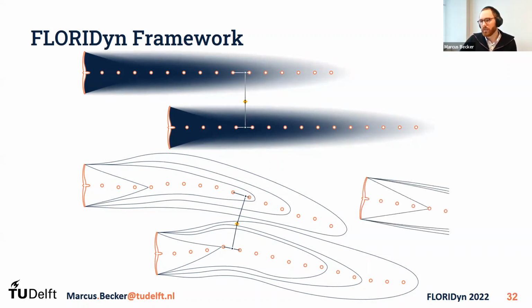And another advantage of this is that we can also ignore turbines which are not affecting this marker, which then reduces the computational cost. And this is an interface that is very easy to implement with existing FLORIS models, where we can just say, we're taking these effective wind farms and putting them into existing FLORIS models and ask them to evaluate them at this one point. And then we can just include existing models quite easily without having to implement them.